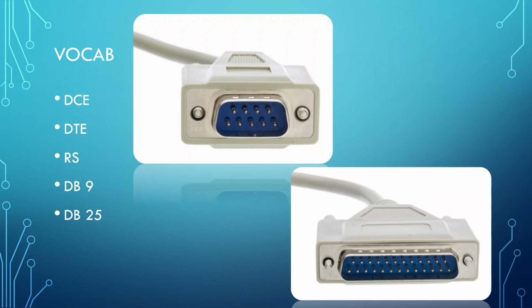Up on the screen right now, I've got what are the standard serial connections. The most standard one is going to be this one at the top right. This is a DB9 connector. If you turned this picture onto its side, the middle shell would look a little bit like a D, and then there are 9 pins in it. So that's where the name DB9 comes from. As I said, it's probably the most standard serial connector you're going to see. The one at the bottom, I think, is a DB25, if I remember correctly. It's out there, not quite as common.